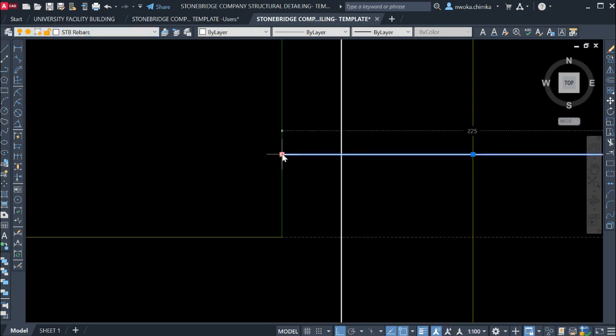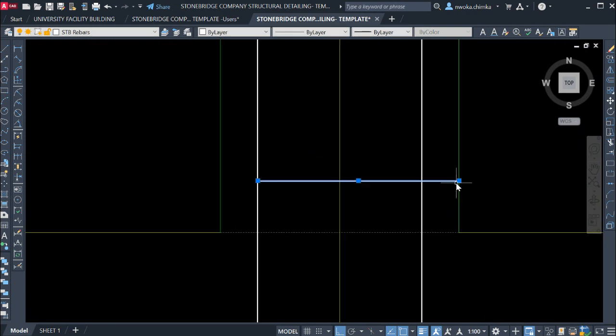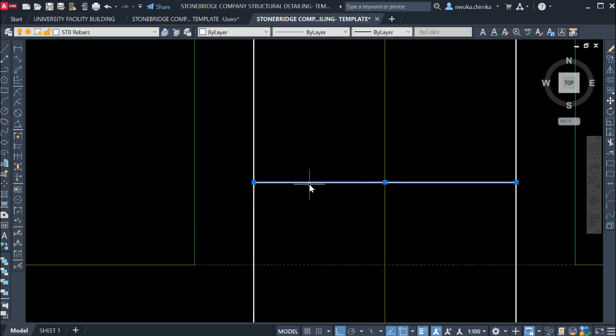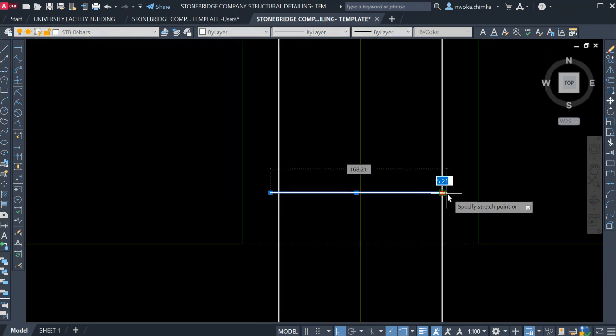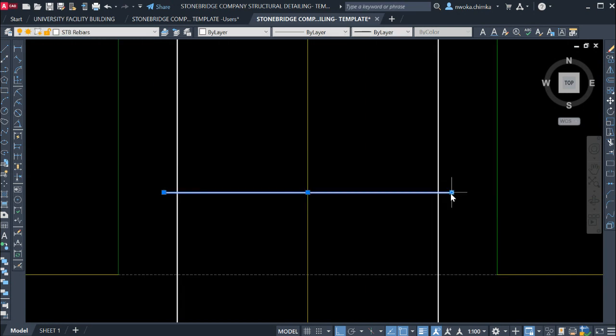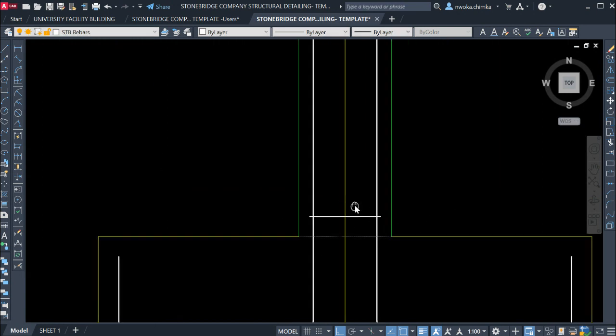And then click on this, take it back here and keep it here, and then go ahead again and keep this also here. Then we will have to offset the diameter of these links, and the diameter of these links is diameter 8. So I have to click on this and click on 8, and do the same thing here also. Click on this, type 8, enter.